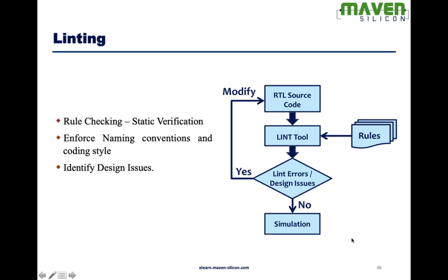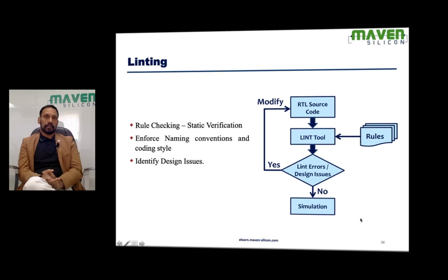Linting. It's nothing but rule checking. Basically, it's a static verification. What it means is we don't write any test bench and do simulation for rule checking. The tool is going to do everything. That's why it's called static verification.